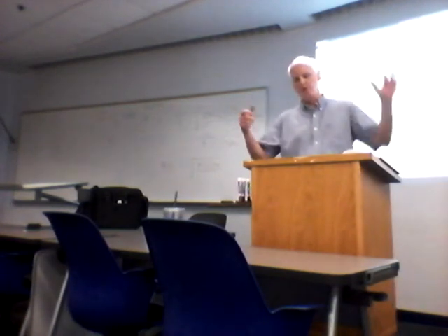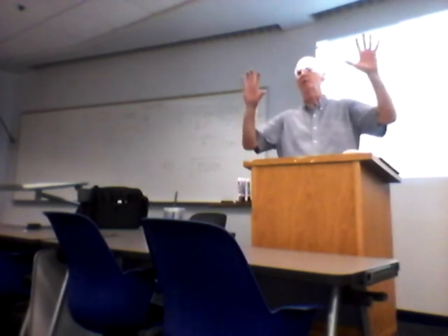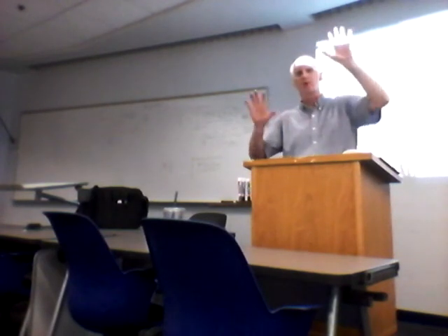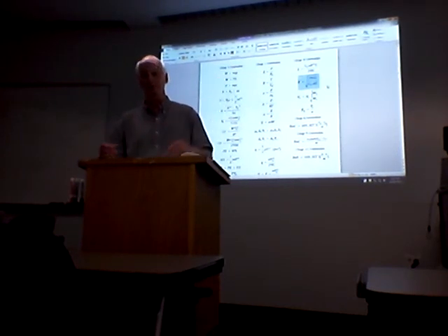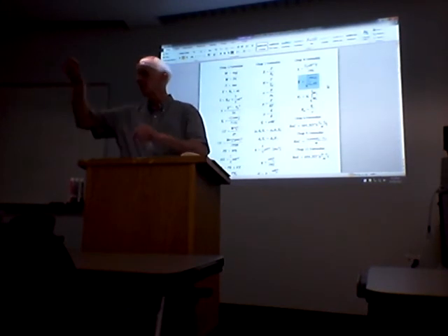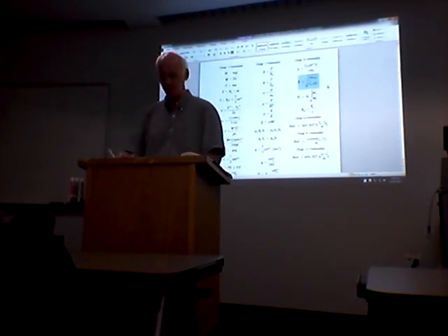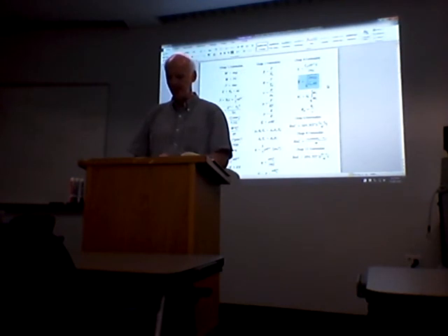Remember that jet aircraft versus propeller-driven aircraft curve, which is derived one from the other. You ought to be able to figure out a best range airspeed with headwind or tailwind. I think I went over that a little bit. Just use the graph, and its tangent line. We talked about thrust and horsepower; they're not interchangeable.